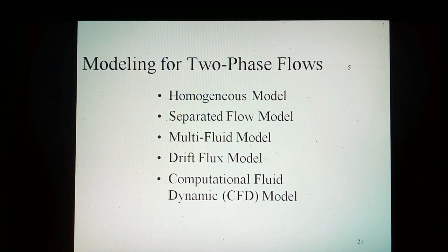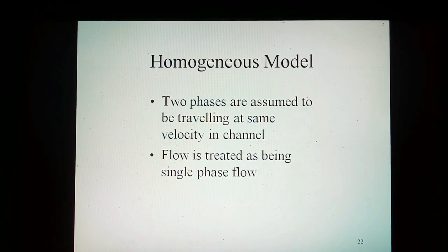Modeling approaches for two-phase flows. A wide range of models have been developed for two-phase flow systems. These include the homogeneous model, separated flow model, multi-fluid model, drift flux model, and computational fluid dynamics CFD model. Homogeneous model.